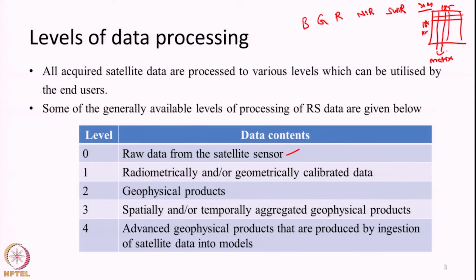You can think of it as a 2D matrix arranged in rows and columns, different latitudes and different longitudes. Each band will produce one 2D matrix array, so you will have 5 matrices. This information is the remote sensing data, and each pixel will contain the DN number. So the output in level 1 will be this DN.